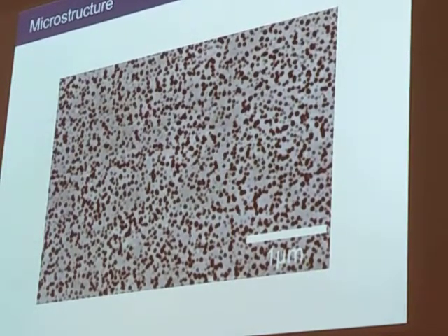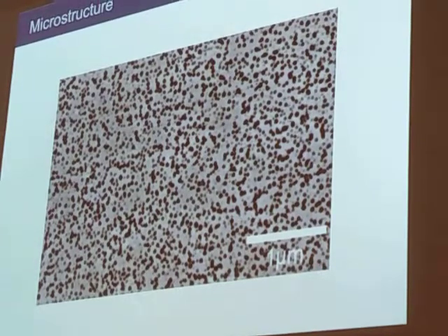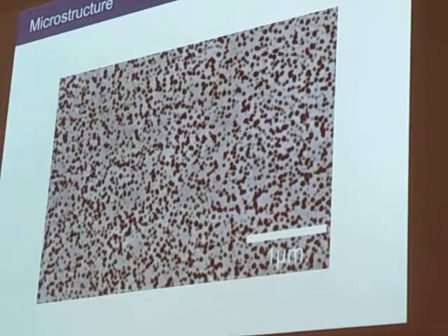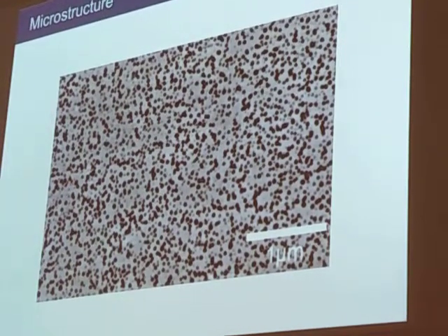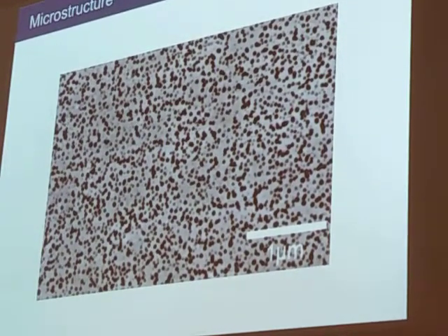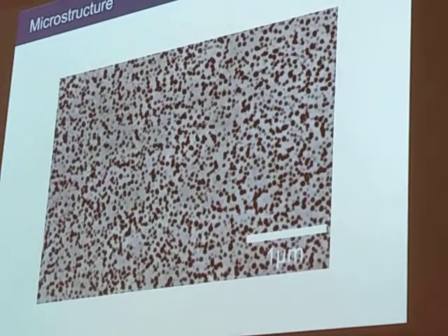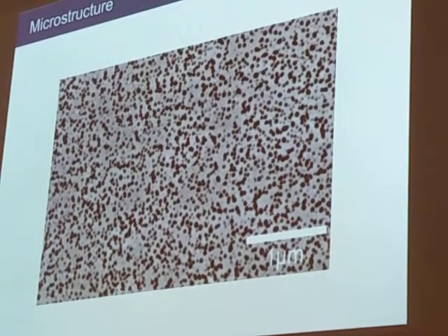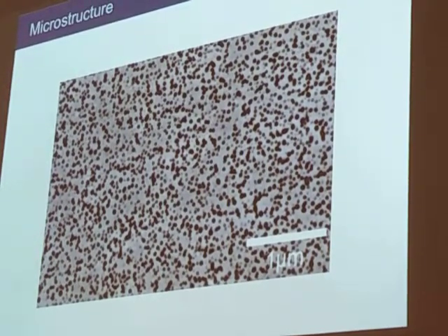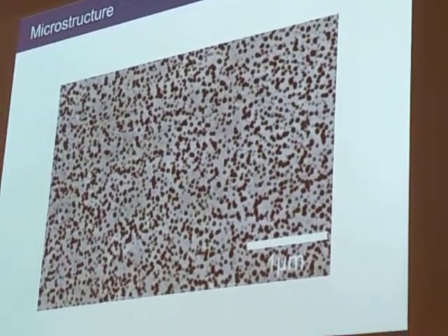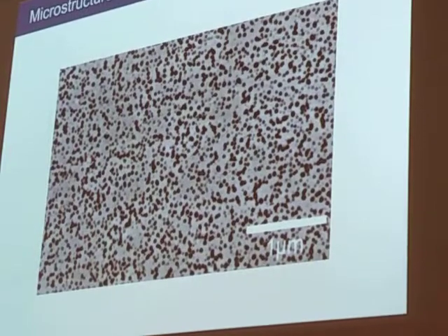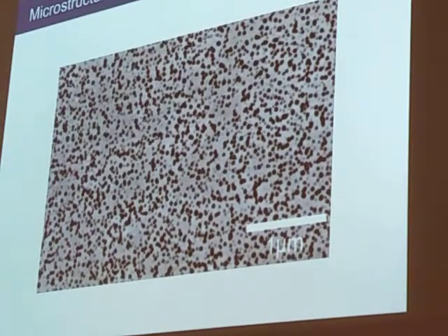And it works a little bit like concrete. As dislocations move through the sample, like cracks in concrete, they get pinned by those precipitates, and they really give the material its strength. So it's vital that we get the gamma prime phase being formed, that we avoid about 60 other phases that could be formed in this material that we do not want, and that those precipitates are of the correct size and do not evolve with time, to tell us that we've got the heat treatment process correct.